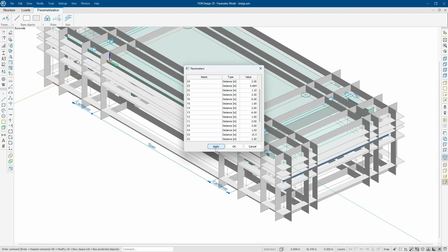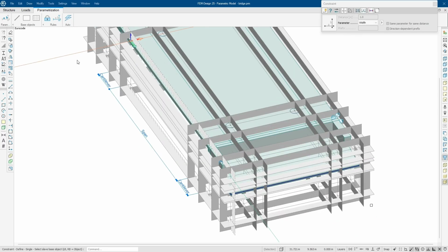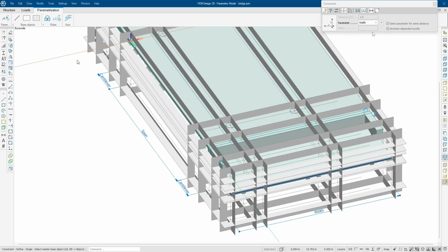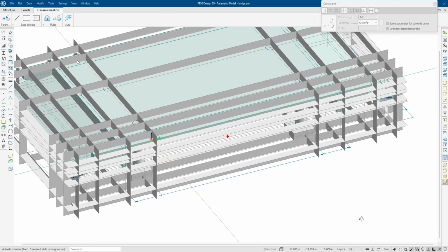So all those constraints that have been defined correctly, we can already modify ourselves, and then put some new constraints in the model. So the automation can help you put those locks and planes automatically. So you just draw it and run the automation and fix the rest yourself. So that is a really good way. And now we just define what the automation cannot define correctly. Let's say I want to define the width, what is from here to here, the total width of the bridge deck, and let's say that we want to define something else like this chamfer part. We can define it manually.